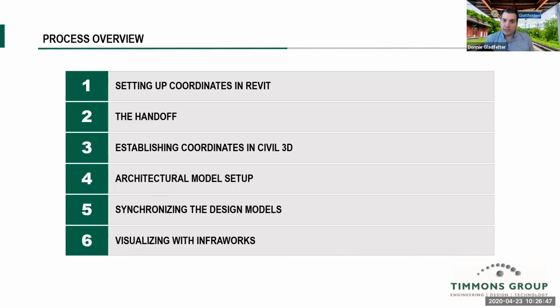If it doesn't get released for some reason, the alternative workflow to mimic the XML is to have the civil engineer export their AutoCAD or Civil 3D drawing with the TIN, or triangulated irregular network, displayed, and in Revit build the surface from the actual triangles that Civil 3D is building, not the contours. At all costs, I would try to avoid building things from contours and build them from the TIN lines instead. So a workaround would be to go back to the basic drawing format approach.